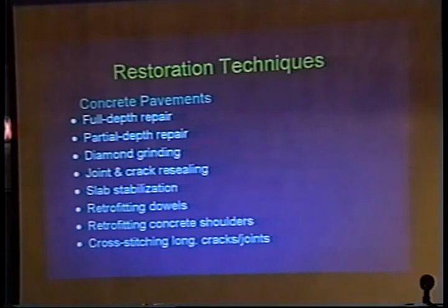Partial depth repair, taking out a section of the top portion of the concrete pavement that might be deteriorated and causing you some problems, and replacing it with a bonded inlay. Diamond grinding, where we're taking off the top surface layer of the concrete pavement with a diamond saw blade drum. John Reese is our next speaker after Jim. He'll get into that considerably. Joint and crack resealing is another method, keeping incompressibles out of the joints and also keeping moisture out of the joints.